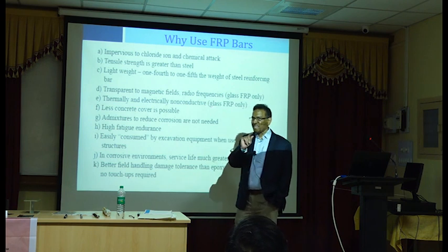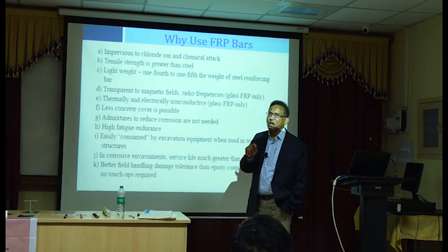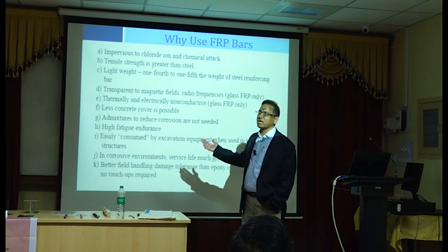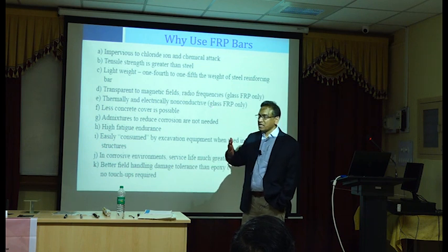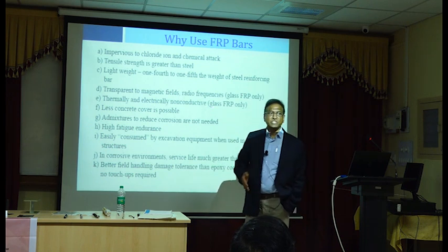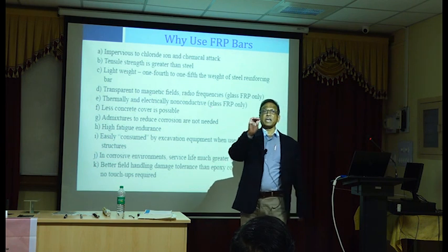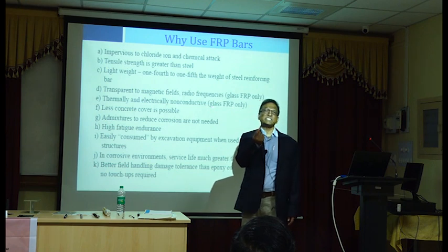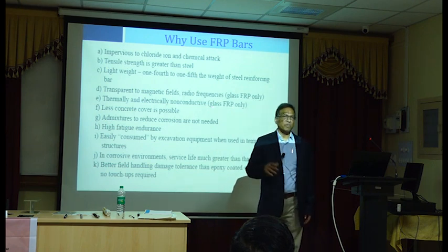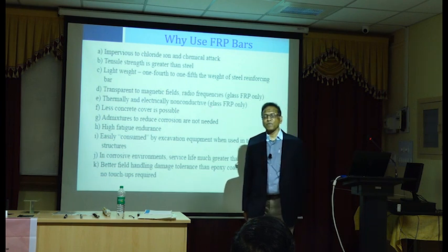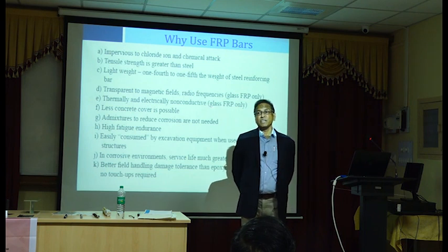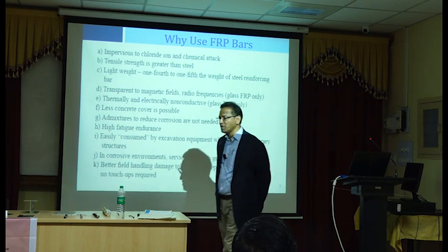But remember one thing. There are always many times, in order to prove that FRP is better than other steel reinforced members, the producers will put a lot of pressure on you to say, okay, use concrete cover of 1/4 inch, 0 inch, whatever. 1/4 inch is 6 millimeter, right? 6 millimeter, 10 millimeter, that's enough. Do you really think if you have a 20 millimeter bar, a 6 millimeter cover is enough? No, it's not enough.